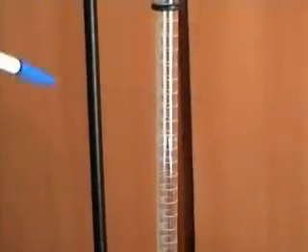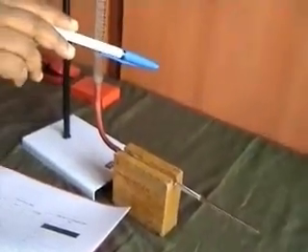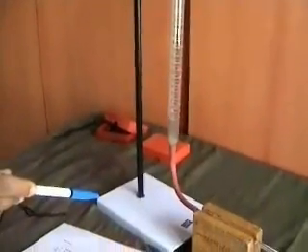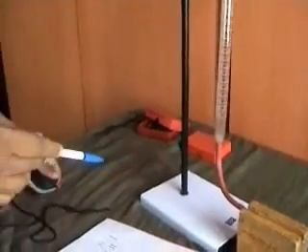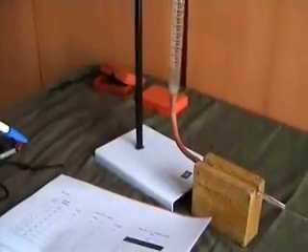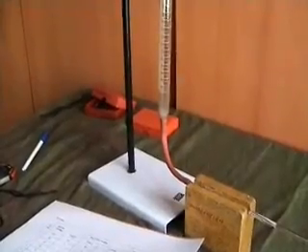Don't disturb anything in the instrument, because if you take out the burette and then do something and pour the water, the height will change. So don't do any changes in the apparatus. Keep it as it is, just only pour water for the second trial and repeat the experiment. We have to now see how to take the height of the 40 cc, 45 cc, etc. and write down. For that, have a meter scale and we'll see how to do that.